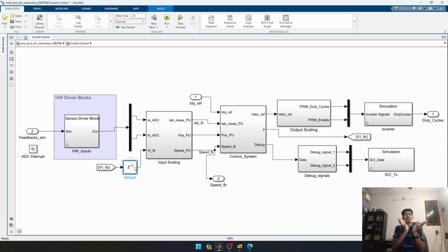So everything is there in the real world, but in the simulation, all these are virtual mathematical things. In this entire MATLAB model, if we connect two things without a delay, the computer will not understand whether the signal is starting here or here. It will create a circular reference. It is paradoxical and impossible for a computer to solve. So we have to add a unit delay, which clearly tells the computer the signal is starting here and propagating in this direction.